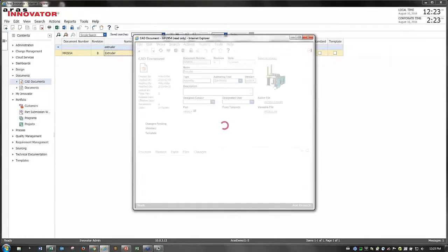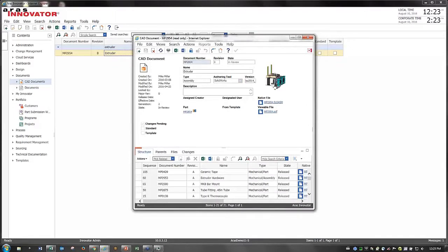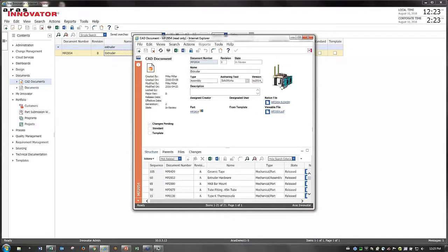Being a CAD user working through CAD connectors, your CAD users, once they get their activity, are going to work through EPDM or SOLIDWORKS and search for their parts in Aras, directly through the SOLIDWORKS interface or through the EPDM interface. The EPDM is put in sync with the workflow progression in Aras as it moves. It's going to actually move it through the EPDM workflow and keep those in sync. So, as if I was a CAD user, I could go into here.